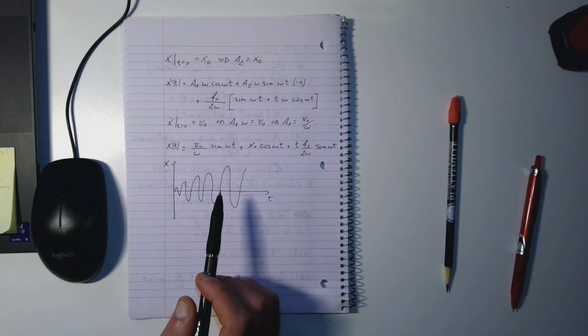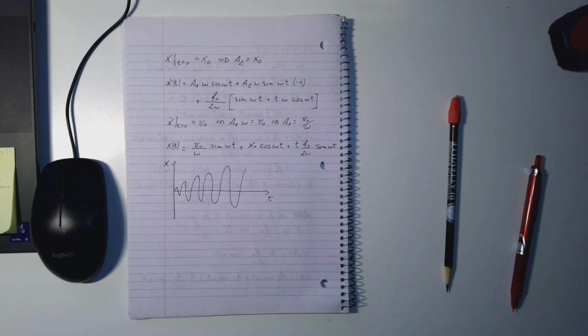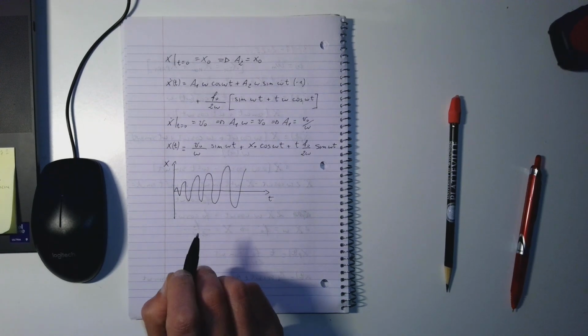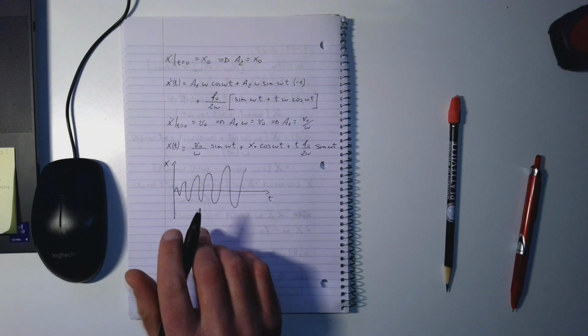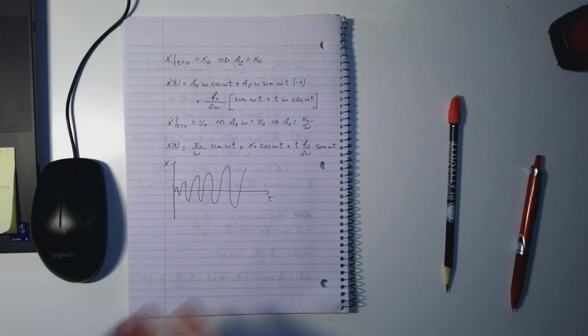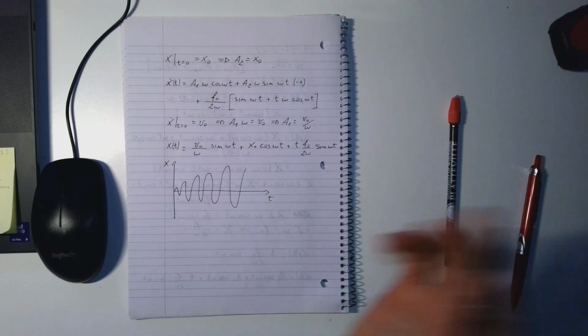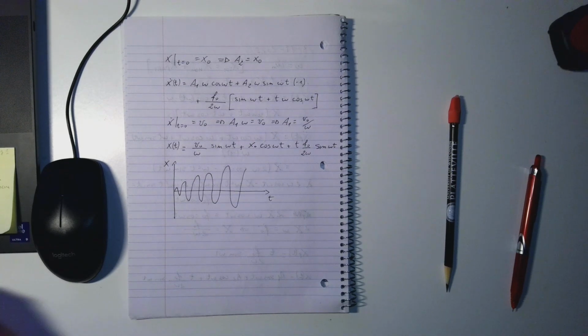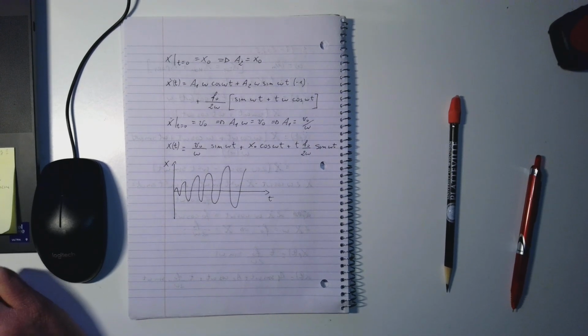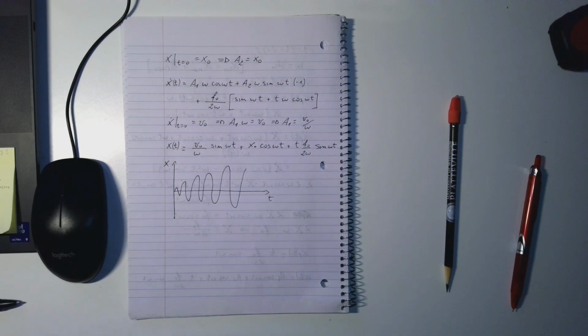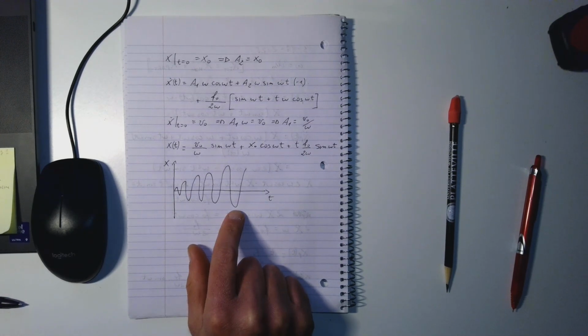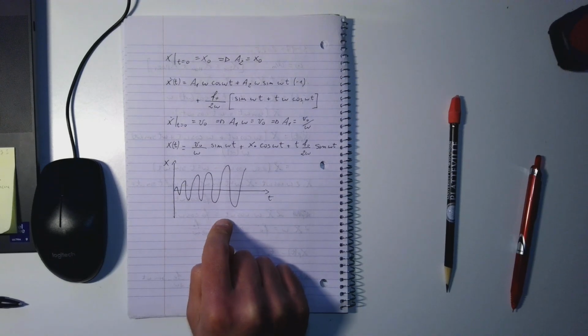So now I think it's a little bit more clear why we always need to look at the natural frequency of a certain structure, and why we always want to avoid that the frequency of the external force is the same or very close to the natural frequency of the system. Because when we excite a structure with a force that changes in time with a frequency that is similar or the same as the natural frequency, the response looks like this, and this phenomenon is called resonance.